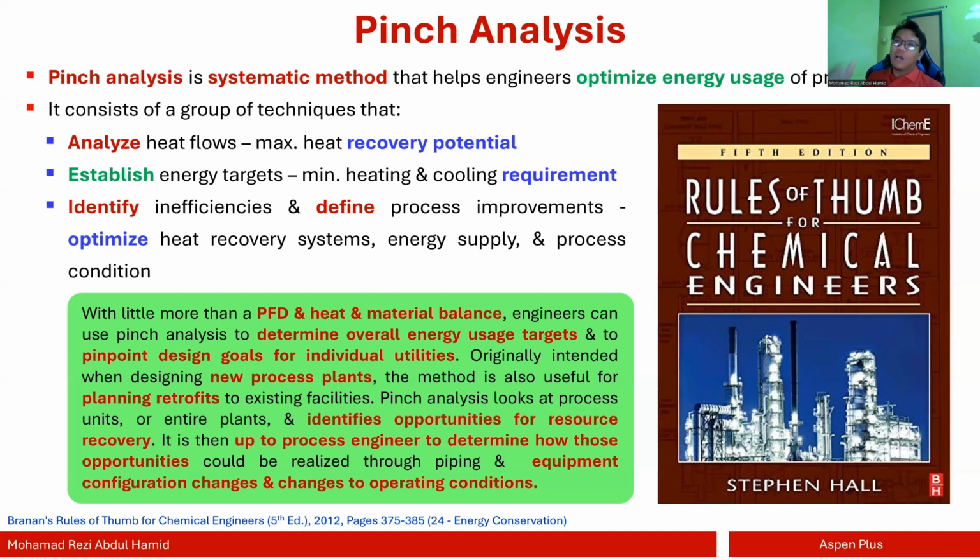So after you do the analysis, there might be some unknowns that cannot be put into the pinch analysis. But as an engineer, given the ideal case, you also need to take information from the real case, and then decide whether you should go with this design, or whether there is a possibility to change the design based on the constraints that are available.